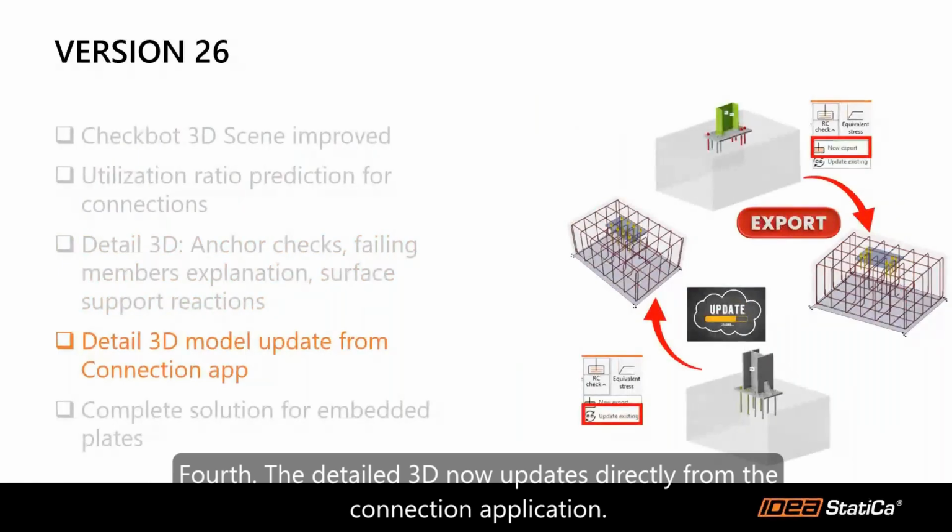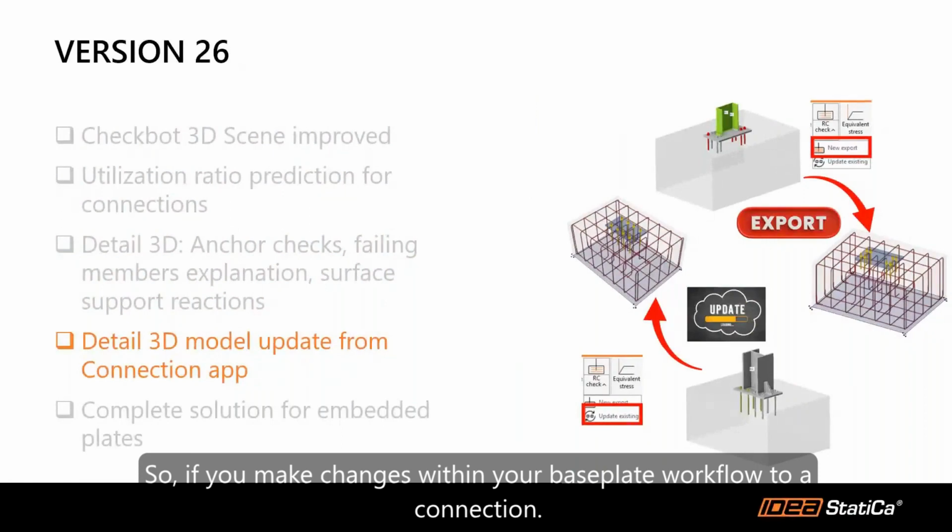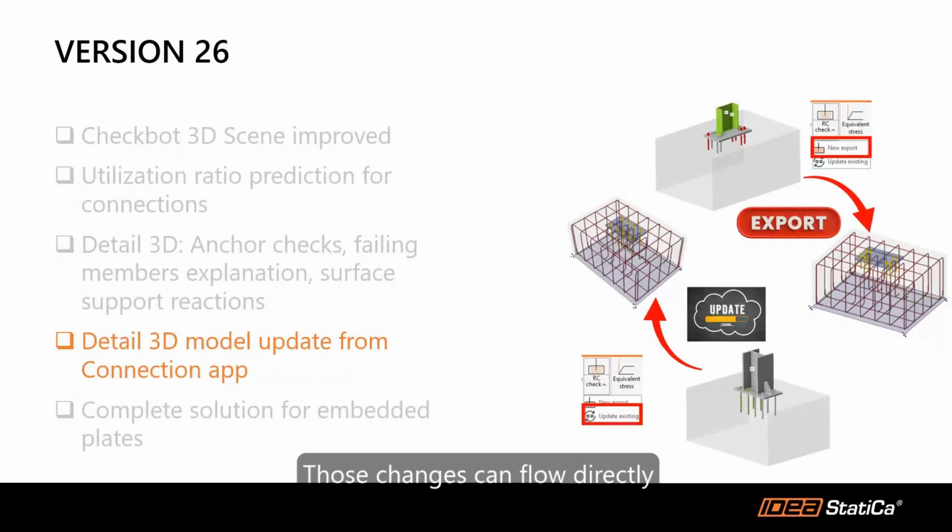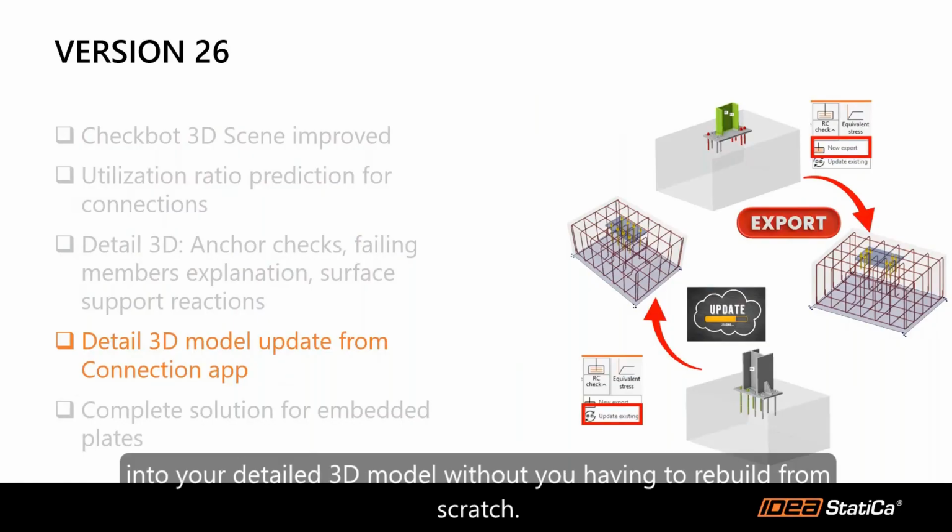Fourth, the Detail 3D now updates directly from the connection application. So if you make changes within your baseplate workflow to a connection, those changes can flow directly into your Detail 3D model without you having to rebuild from scratch.